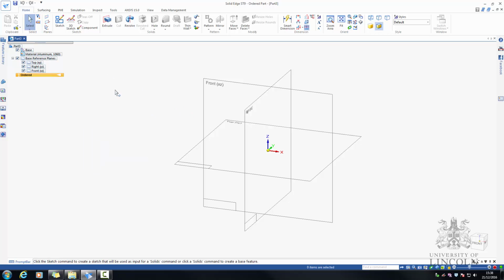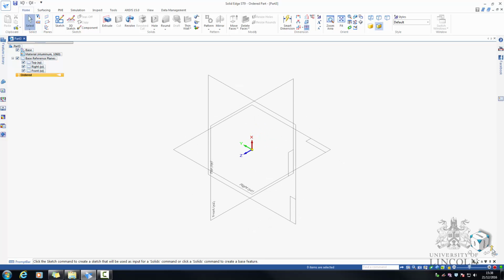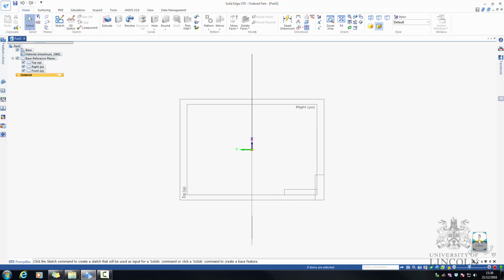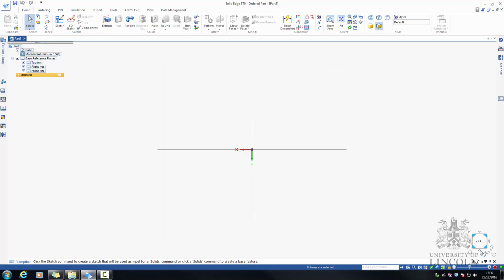Okay. So with that, we're in a 3D environment at the moment. We can look at things in 3D. If you want to control what the 3D looks like, there are a number of tools to help you do that. You've got the view cube down here. You can use that to rotate through isometric 90 degrees like so. You can choose to look at different isometric views of the corners of a cube. See where the blue things are? I could left click there and you'll notice me rotating around my views. I can also look at it from an angled side, like so, or from an orthogonal point of view: top, right, or back as it actually is, left, front, right, etc. Bottom, and you can see here that we can rotate around things.